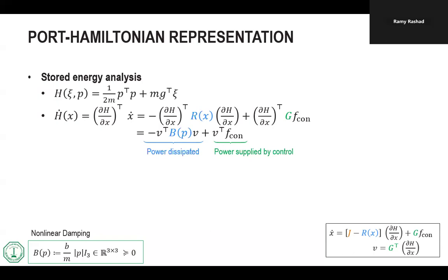You don't even need to do math. You can even just look at the system. And this is again the power of the Port-Hamiltonian, because anything in the J part, the skew symmetry, will always disappear from the energy balance. Anything in the R will always appear like this: there's a minus and the gradient of the Hamiltonian, or the co-state, transposed, multiplied by R and the co-state.